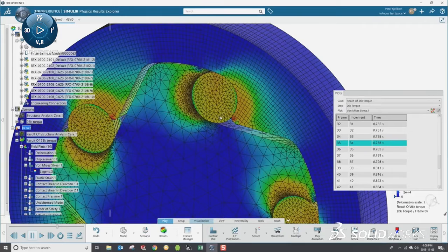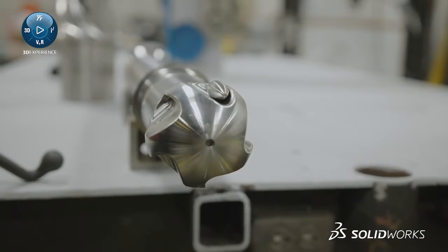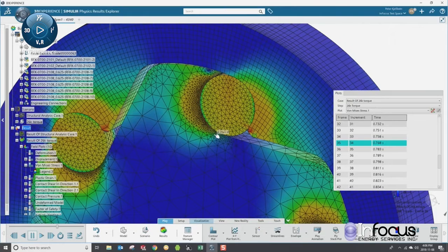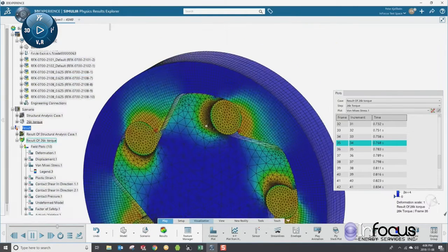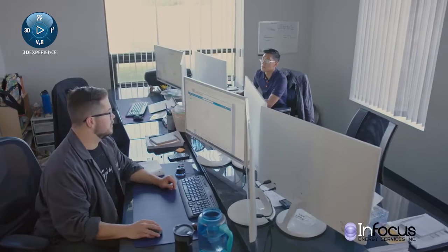This is the drive shaft for our 7-inch reflex motor, and what we're interested in simulating is the bearings inside the drive system. In SOLIDWORKS, we only had one of these drive pins simulated. In SSE, we were able to take all of them, the entire system with the inner drive shaft and the outer drive shaft adapter, and run them much quicker.